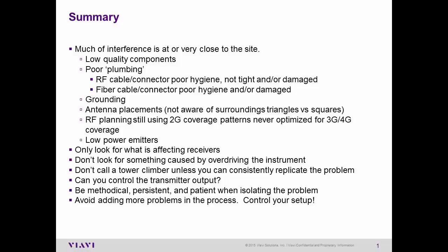Don't call a tower climber unless you can consistently replicate the problem, meaning that you know how this problem manifests itself. If it's something that's self-inflicted, you should be able to use your own transmitter to recreate the problem, so that when the tower crew gets there, you can clearly see where they're able to help replicate that problem by tapping and torquing, or that you can clearly see the problem has been fixed as they tighten or replace components. Can you control the transmitter output? That's really part of replicating the problem.